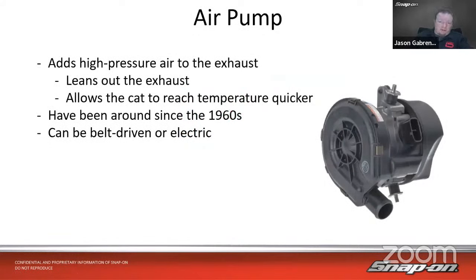Next thing is an air pump. So we've been using air pumps since the 1960s on vehicles. We have mechanical ones back then, and then nowadays the modern ones are electric. Adds high pressure air to the exhaust. So that helps lean out the exhaust in a way.